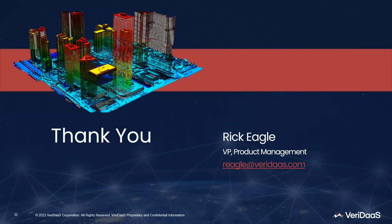Yeah, happy to do so. So some very early testing, and this was, I don't know, 3 or 4 years ago, against some sample data that we got from VeriDaaS, seemed to indicate that the voxel sampling methods produced a very regular distribution of points above ground within vegetation that does not work well with some of the metrics that are based on the irregular distributions of point returns above ground.